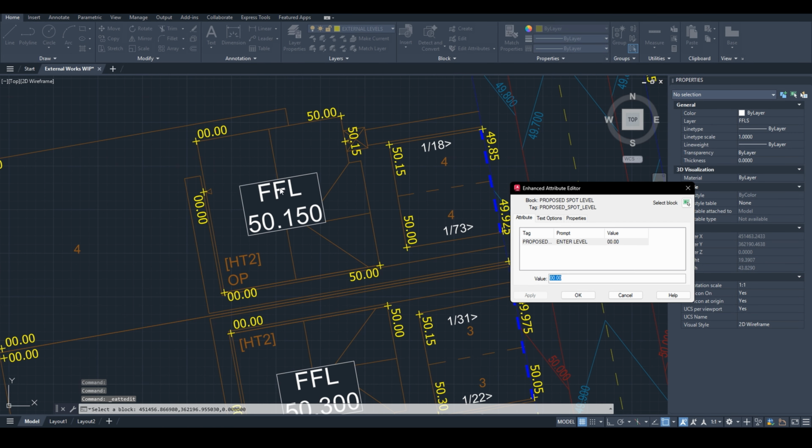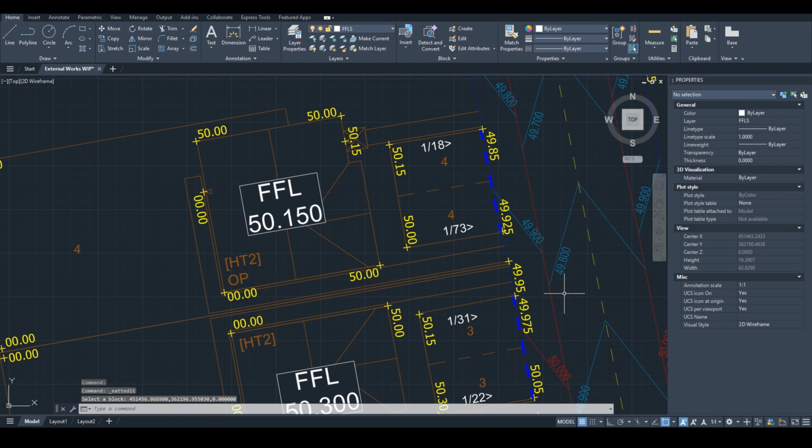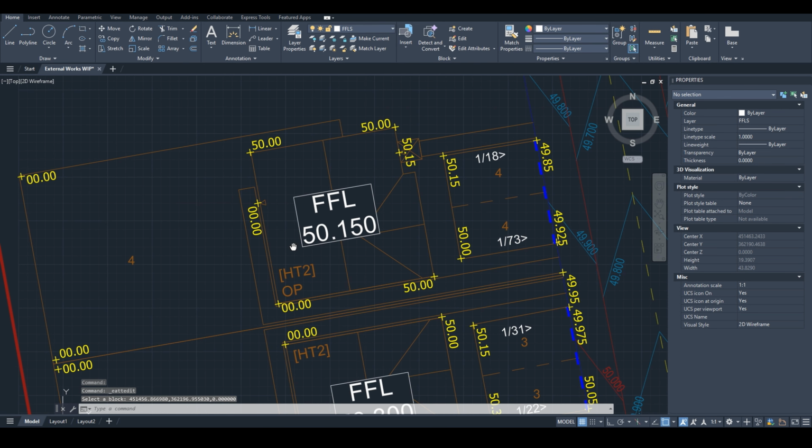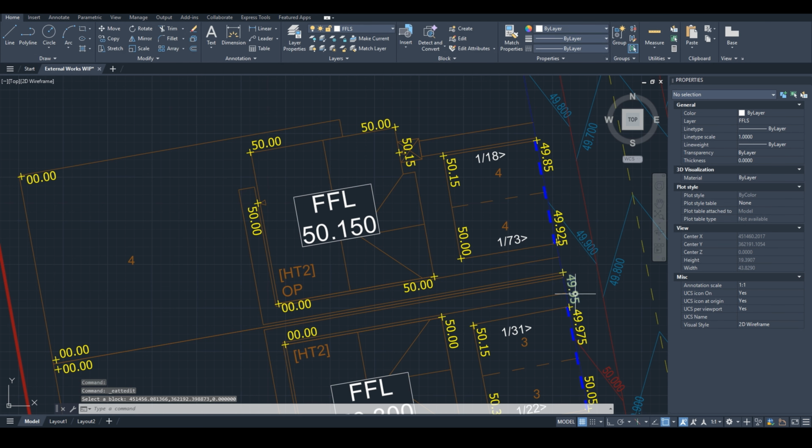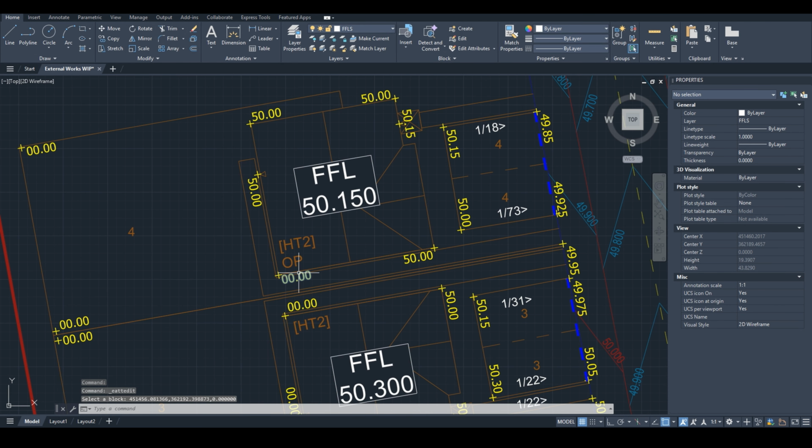As per the general rule of thumb, I will put this corner 150 mm below the floor level, as there aren't any constraints here. Alternative entrances should generally be 150 mm below the floor level, so this back door will be set at 150. When working on closely adjacent plots like this, I like to work on the lower plot first.